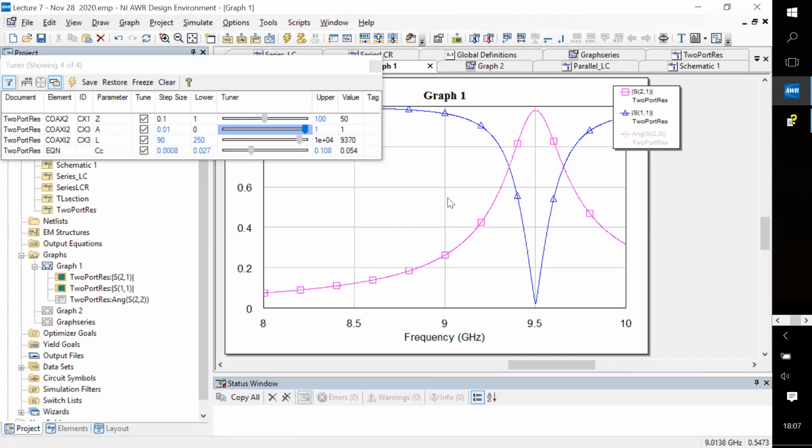Okay, and you can sort of understand this is because as the waves are going back and forth, because they are getting lossier, they're not coming back with the same amplitude. So that affects the interference conditions. Okay, so this is another thing to remember. These concepts about what causes the signal to be not perfectly transmitting or increase reflection, these things will allow you to understand what's going on with your device when you're actually measuring a real one. Because it'll tell you, okay, is this something because my capacitors are asymmetric, or is it because I have loss? All of those things sort of help you.